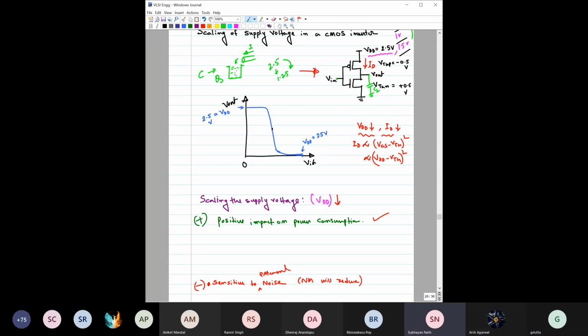Sir, RC is actually changing. R is changing, and it can be explained. We are looking into the drain side of basically the NMOS portion. We know that R will be roughly proportional to R naught. When ID decreases, R naught will increase. So you are saying that the resistance is also changing. Yes, sir. Okay, so the resistance is also changing.